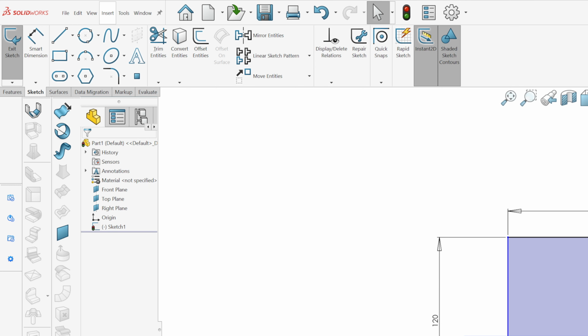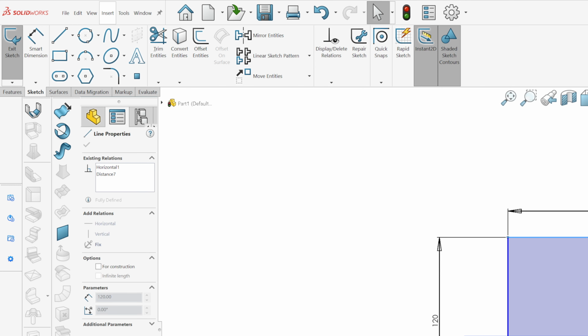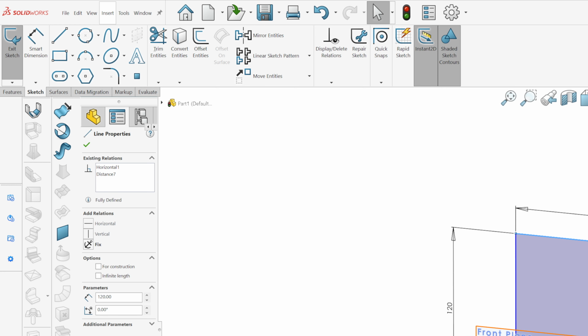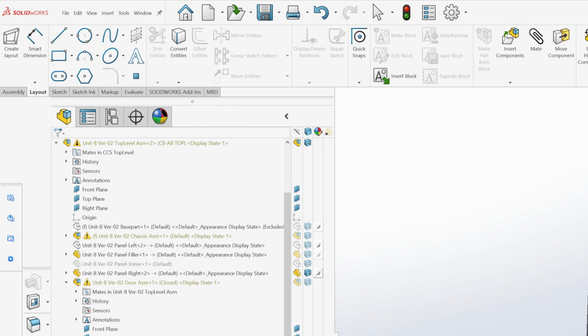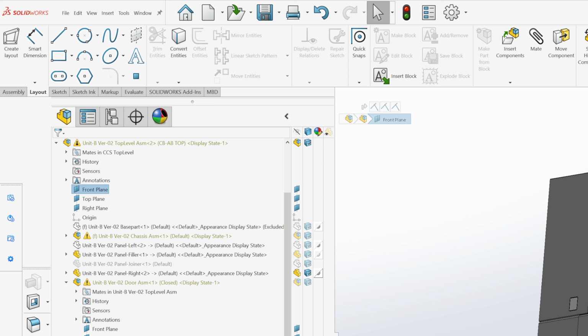Now the item is locked in. I can't raise it up, I can't move it down, because it knows it always has to be 120 off of there. So that's like having it sitting on a counter. When we're working on massive assemblies, it's the exact same thing. I have this, and there's an engineering requirement, an actual requirement, that this item cannot be higher than 36 inches off of a counter. That's a regulation within a store.